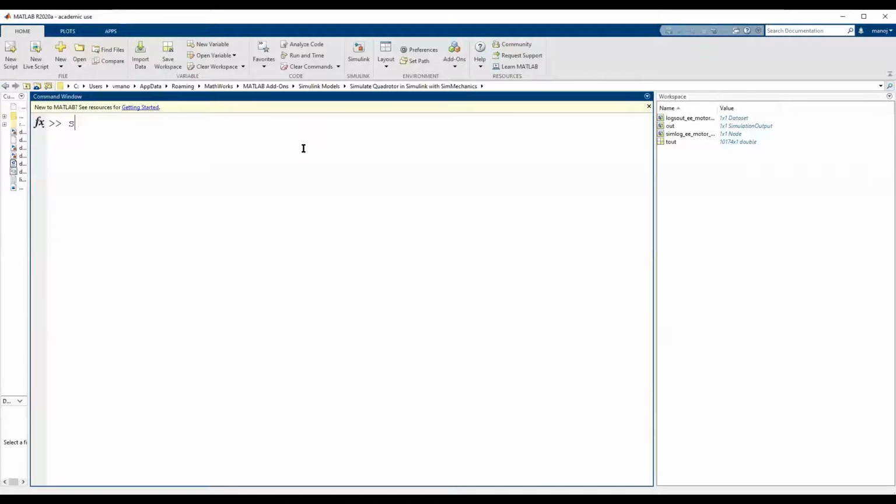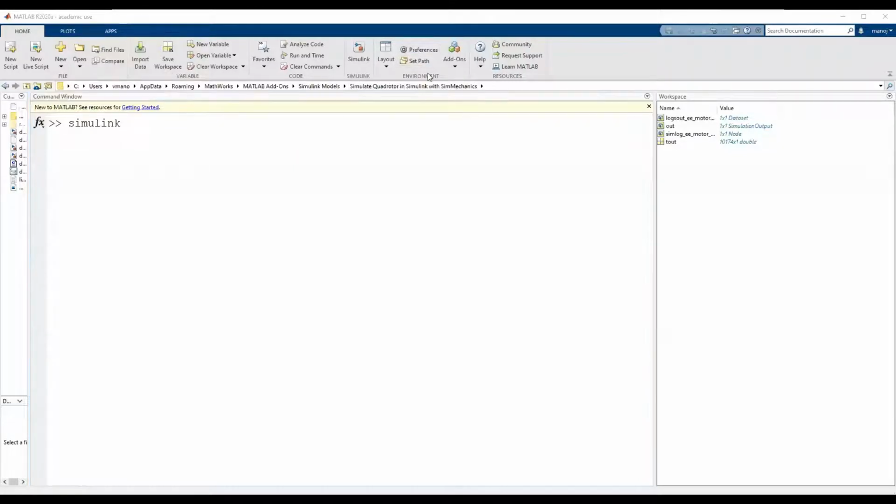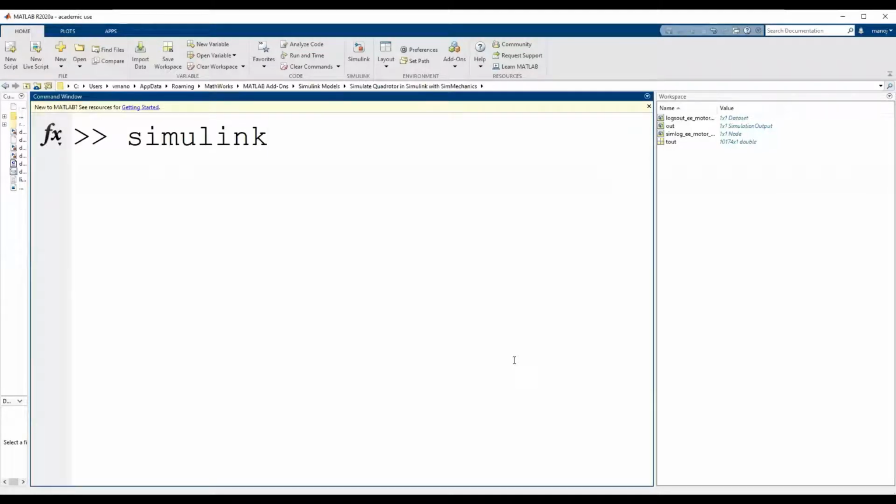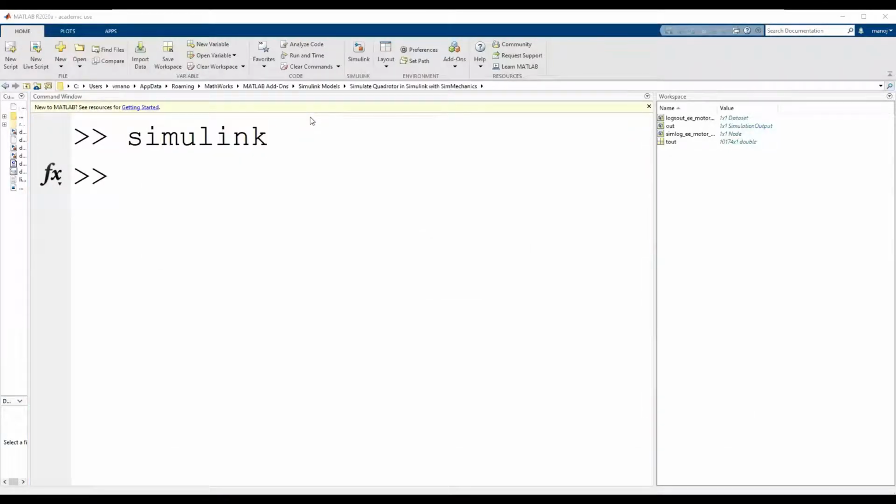Can you able to see that Simulink? Or I will increase the font size. Okay, Simulink is here. So just type simulink and press enter, or you can see the block here in my top window. Go to Simulink and click this. So I'll have my model. I'm going to open my blank model. Okay, create a model.